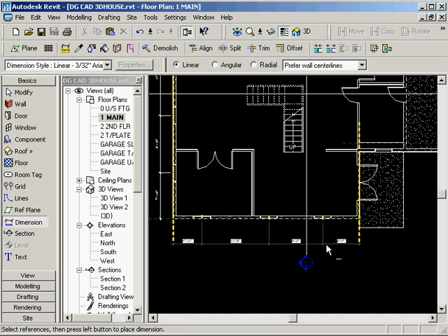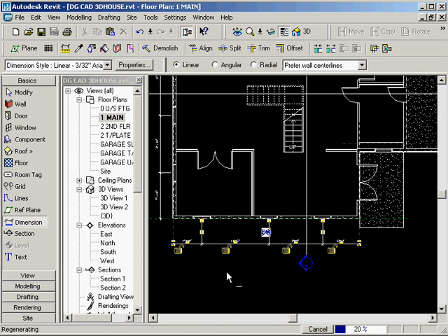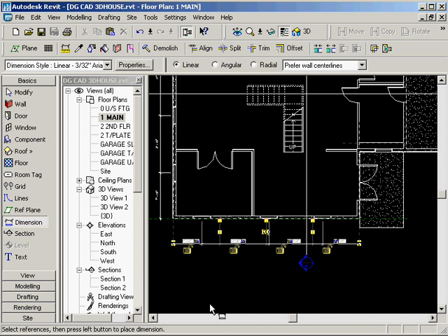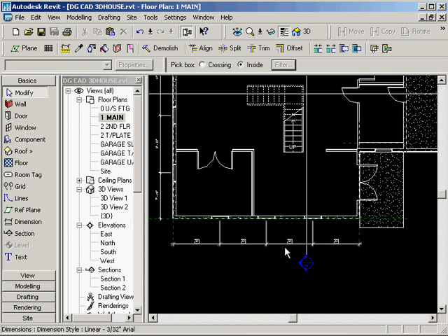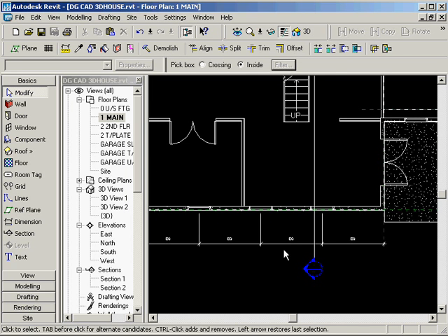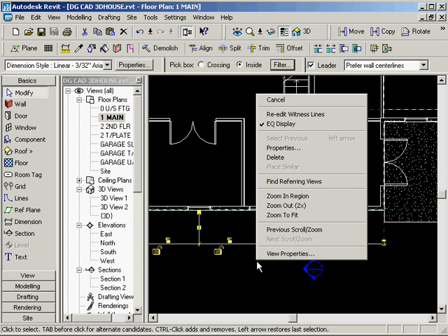Here to here. Place. And then we hit our equal. Okay, equal is going to equally space all those objects in there. Of course, in the elevations and in the plans. Okay, and then I can further lock those dimensions. Okay, I don't need to lock them. Now, right now it says EQ for equal in there. I can click on here. That's what I was thinking of.